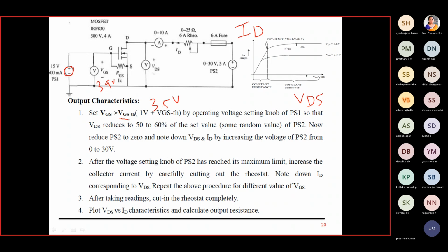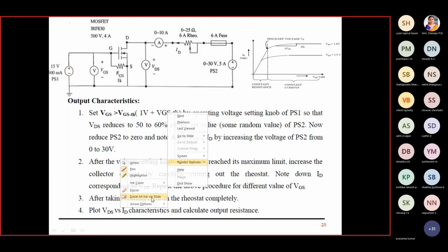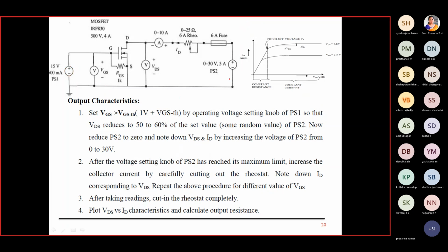Why we do this is, if you observe in this experiment, in case you make the PS switch 30 volt, the same 30 volt is available here. As I told you, this is VDD, not VDS. VDD is 30 volts fixed, but VDS need not be 30 volt. It may reduce also. Then actually this is VGG in fact, but in this case there is no resistance there. VGG and VGS both are one and the same. Let us say VGS only, the supply voltage.